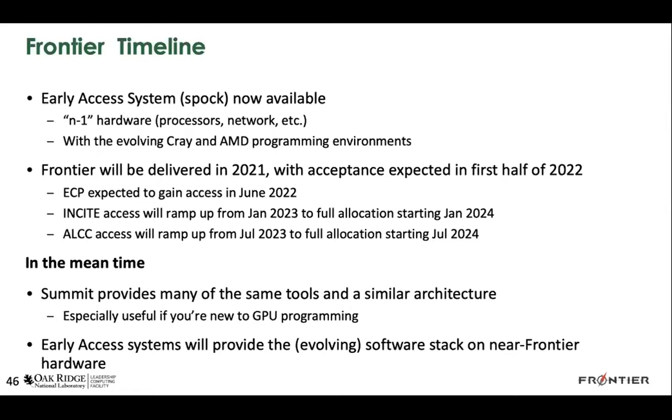Frontier will have the MI200s. The CPU is connected to all the GPUs by PCIe Generation 4, and it allows host-to-device and device-to-host peak data transfers of about 32 gigabits per second each.